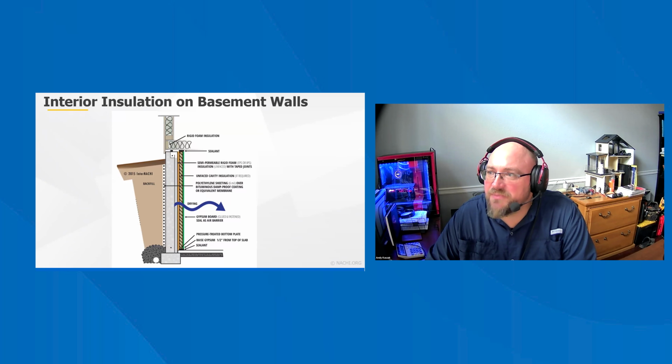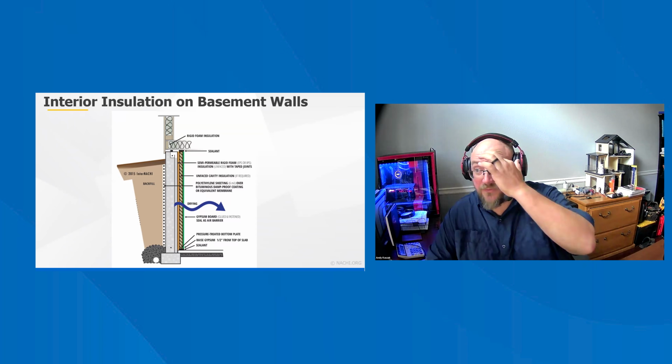A finished basement should be insulated around the perimeter of the basement's exterior walls, and the basement ceiling should not be insulated. As a home inspector, you may see the problem where there may be insulation in between the finished basement space, the conditioned space, and the floor above. The finished basement walls should not be insulated with a type of insulation that is sensitive to water. It should be an insulation that is relatively water resistant.